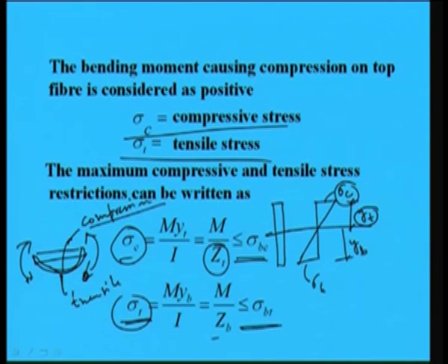So the section is undergoing compression here and tension here. However, it is not always true, because it depends on the type of moment that is going to develop at that section. On that basis, whether the bending stress will be in tension or in compression depends on the type of bending at that particular section.